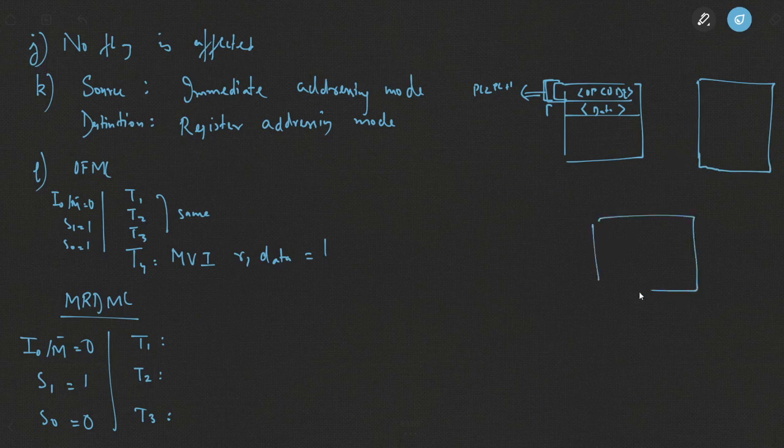In the last three instructions that we have studied, the code was given here, and at the next memory location, since this was a single byte instruction, it was only occupying 1 byte of space. Fine. So in this opcode fetch machine cycle only, whether there was a memory read or a memory write, we were already incrementing the program counter.